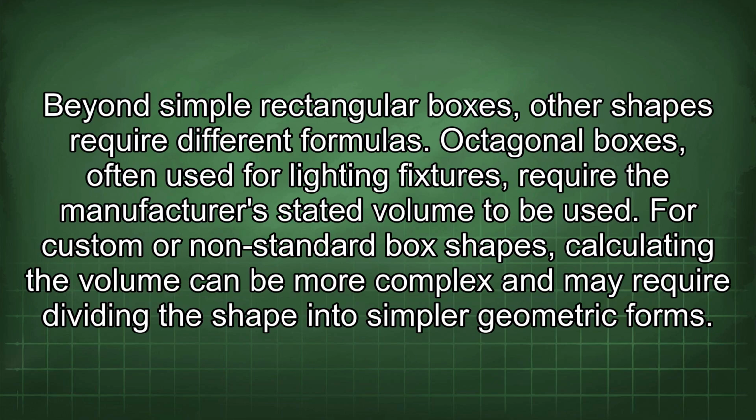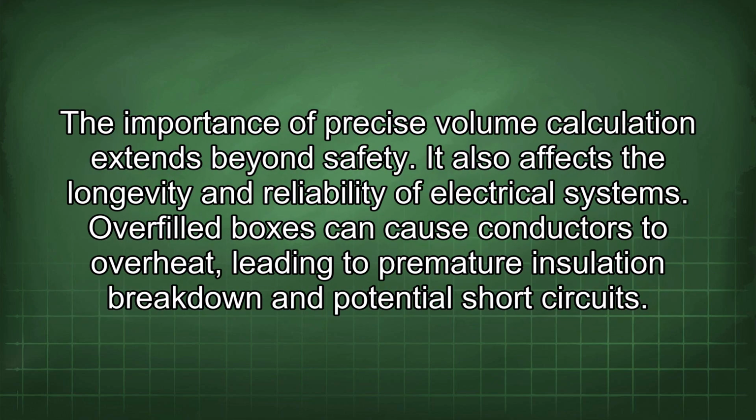Beyond simple rectangular boxes, other shapes require different formulas. Octagonal boxes, often used for lighting fixtures, require the manufacturer's stated volume to be used. For custom or non-standard box shapes, calculating the volume can be more complex and may require dividing the shape into simpler geometric forms. The importance of precise volume calculation extends beyond safety.